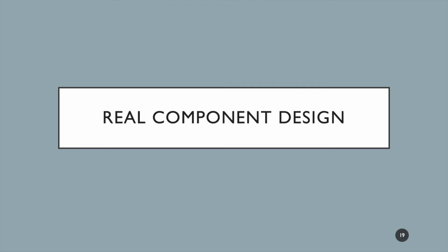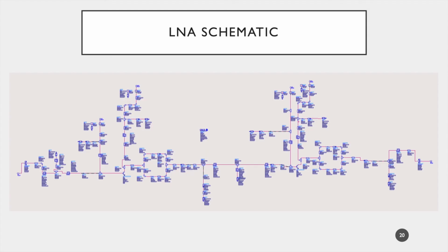After initial results, this design was reconstructed with real components from Cree's process design kit. The schematic for the design with real components is given here. The schematic includes all necessary connection components such as RF and DC pads, ground wires, T's for connecting three components in a node, capacitor connectors. Furthermore, additional transmission lines and curves were added to the design for layout placement purposes.